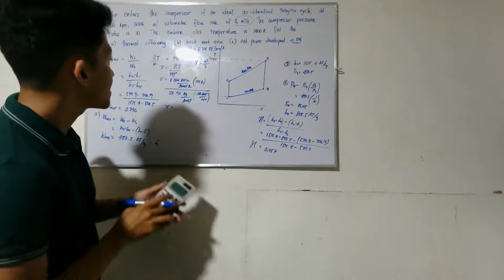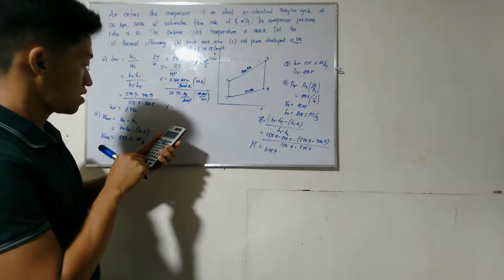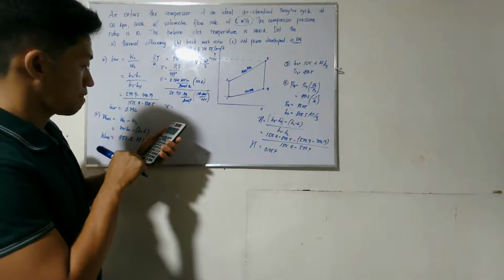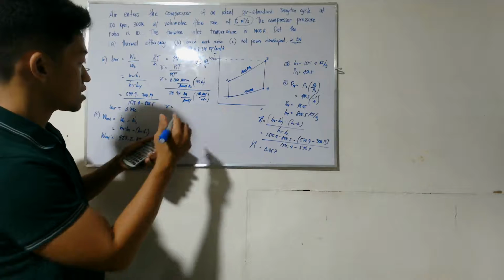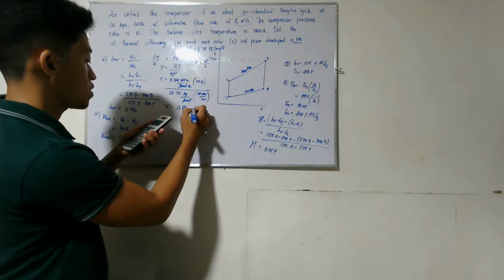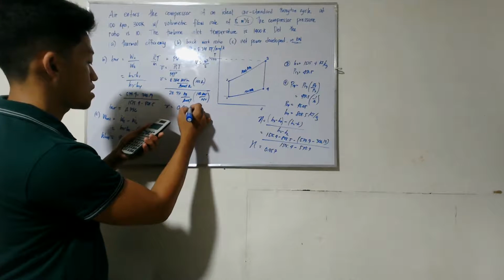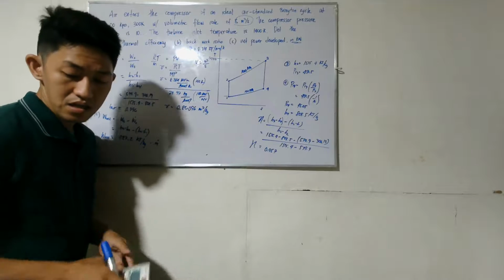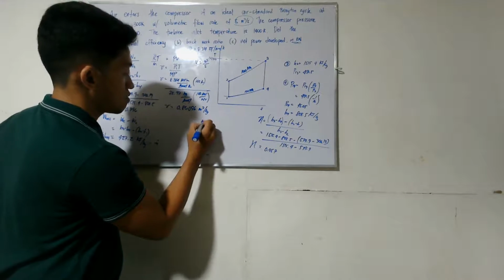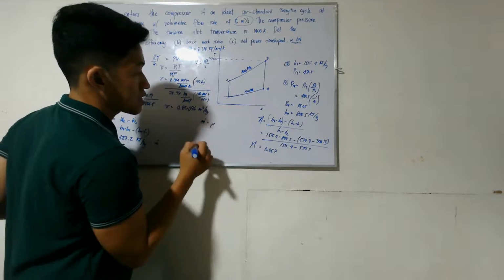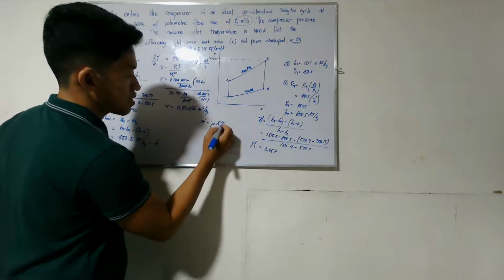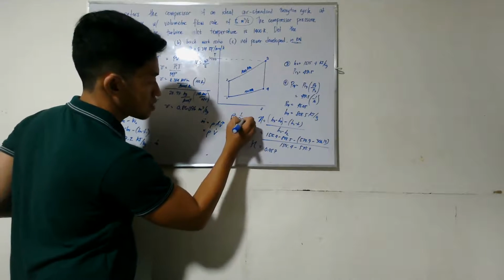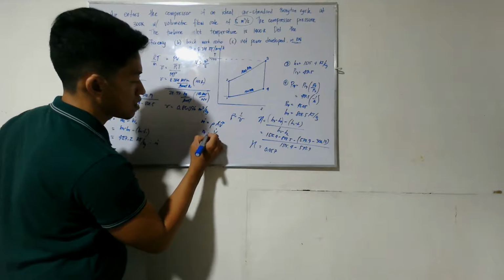So this becomes 8.314 times 300 over 28.97 times 100, which is 0.86096 m cube per kg. Okay, so we now have the specific volume, but recall that the mass flow rate is just rho AV, where rho AV is just the volume flow rate, and then the density is just 1 over the specific volume.